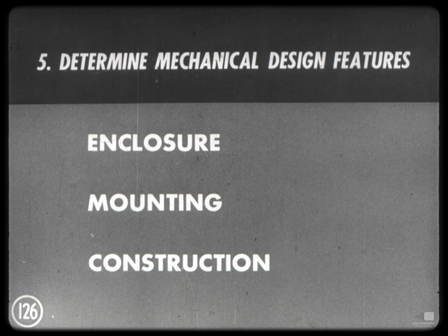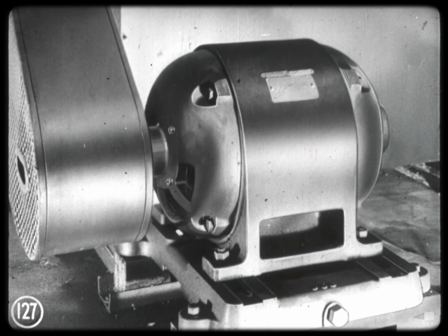Finally, determine the mechanical design features needed for the job. Enclosure and mounting requirements should be checked, and construction features necessary for the job specified. Just 5 simple steps in motor selection, yet they're of great importance in the selection of motors which serve you faithfully, both today and through the years to come.